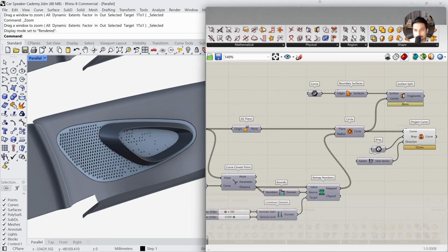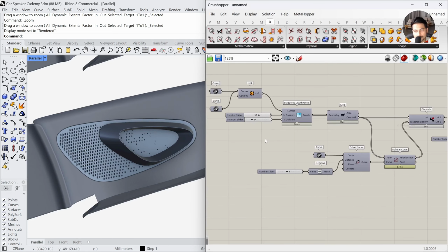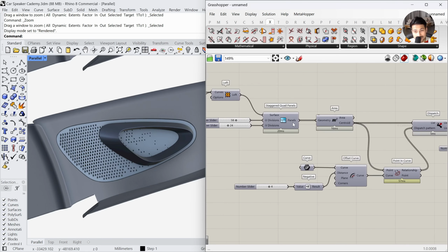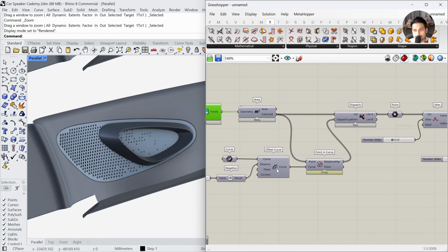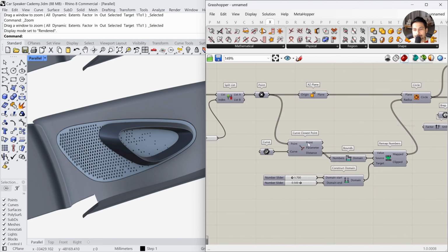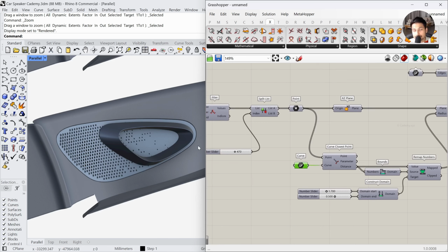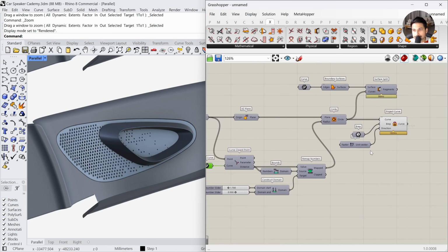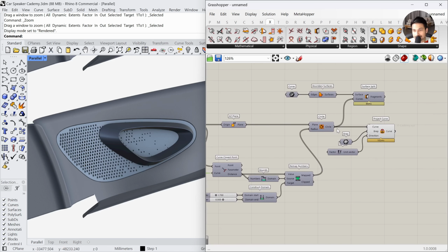You can, of course, modify any of these parameters in Grasshopper. You can also change the panel distribution. You can change the random effect. You can change the radius value. You can also change the attractor curve to a different place. Feel free to modify these settings and create your own texture variations.